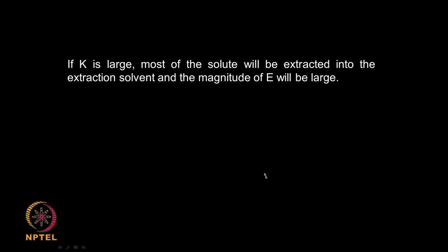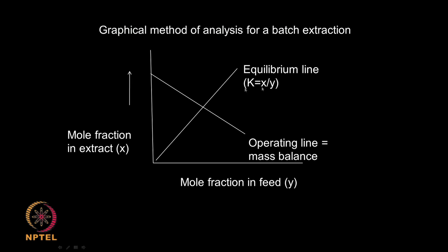If K is large, that means most of the solute will be extracted into the solvent. If K is large, obviously your E will be large. So, the extraction efficiency will also be very large, correct. So, what do you do in the graphical method?